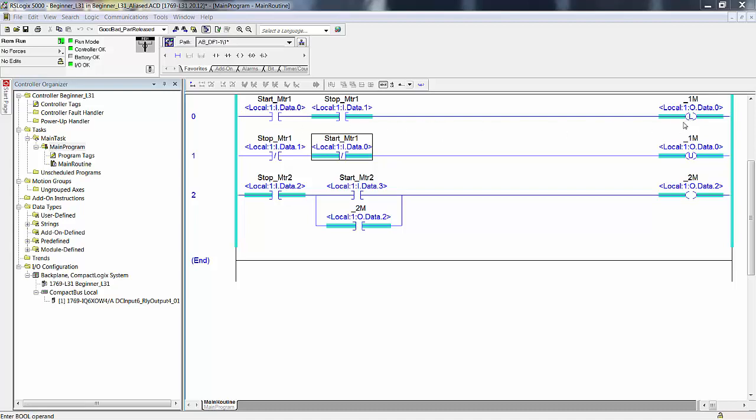So you turn it back off, they stay that way until you make this circuit have a complete path for conductance and energize this coil. This coil then pulls the latch away from the contacts and lets them go back to the normal position.